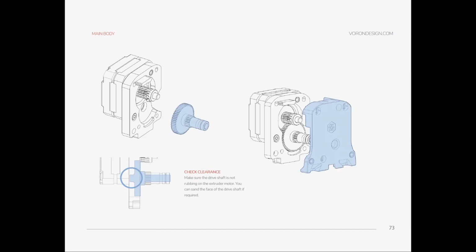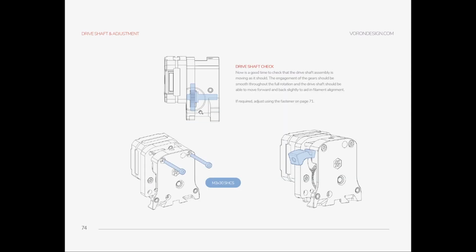Yeah, it was the case for me. The grub screw was not tight enough. It said it's not flush. What I mean with this gearing is that it was scratching these 3D printed parts while it's rotating. I was feeling it when I rotate this while I'm doing the check, at a certain point it was not moving by hand. It's getting stuck, what I mean.